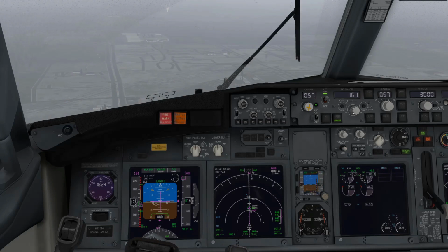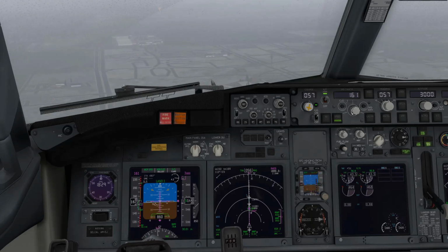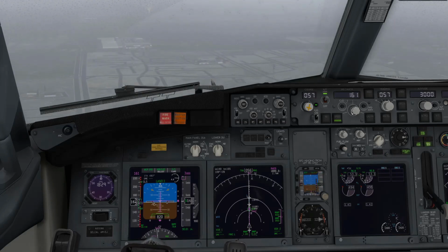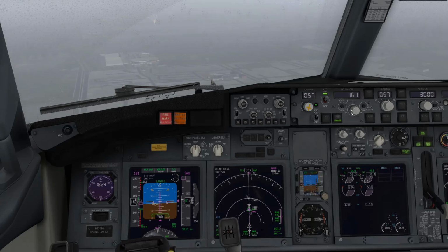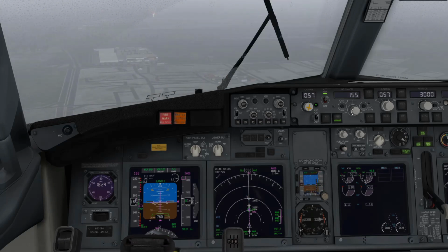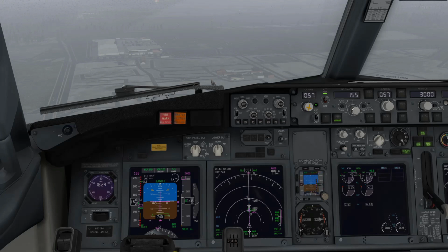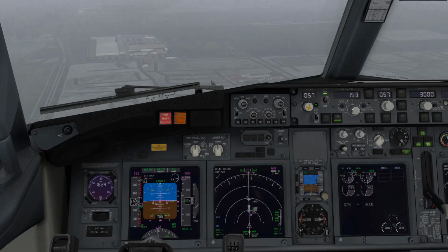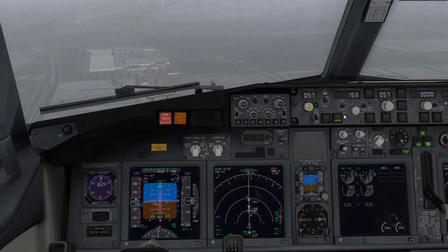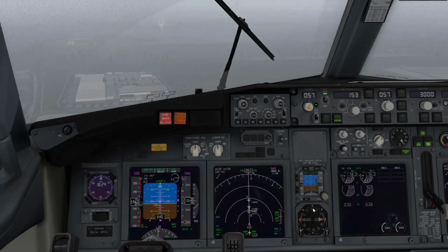Bring some more flap 15 out now. And right to flaps 30. VREF. That was a little rushed. You shouldn't have to do it that fast. So we got VREF at 153.